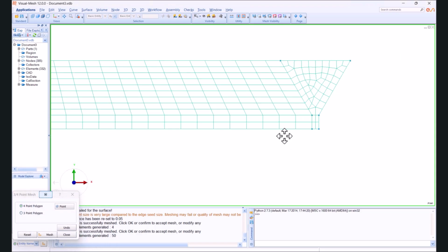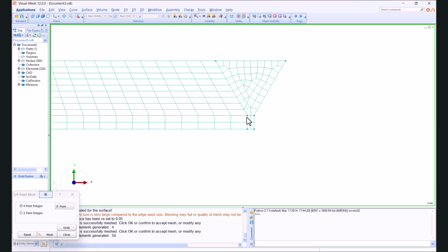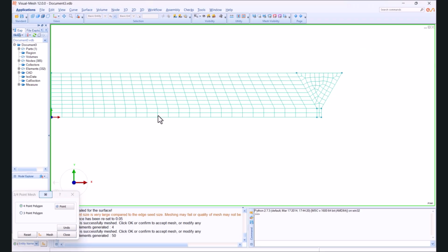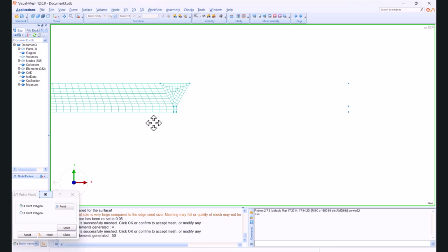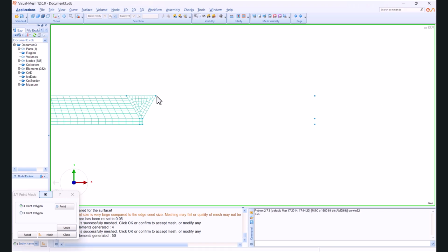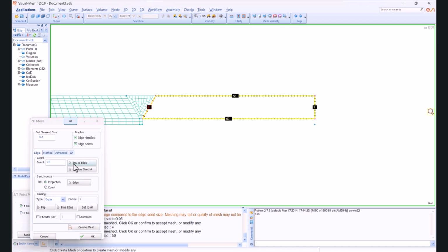It's so crucial to start with this root pass, then creating the left one, otherwise you cannot create the left part, it would give you some error. It'd be the same right over here. We can set the edges 25, 25, and by clicking on this one, left click and hold, then we drag it down.